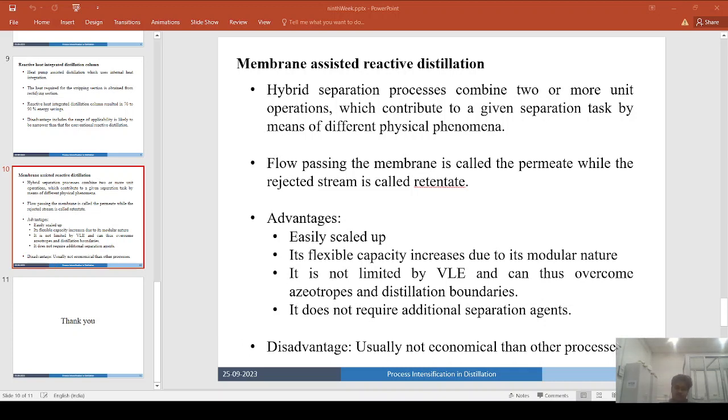The irreversibility associated with the distillation separation operation can be reduced by bulk heating from the microwave irradiation. Other advantages are that the reaction section and the separation stages can be reduced by improving the reaction rate and separation efficiency, which leads to a reduction in the size of the reaction and separation stages.